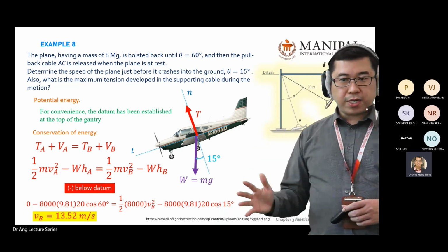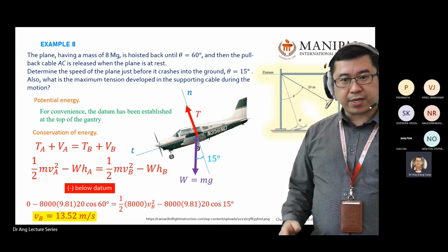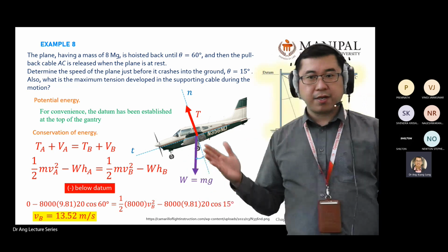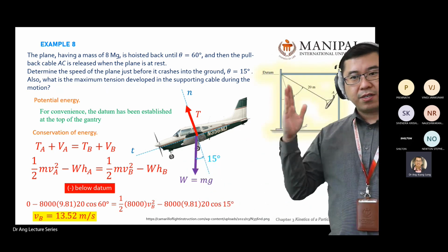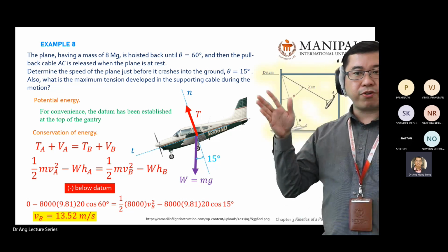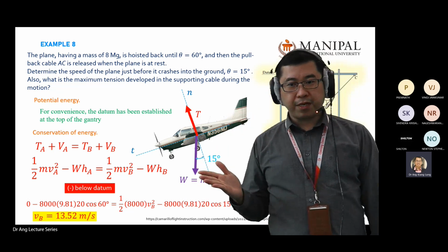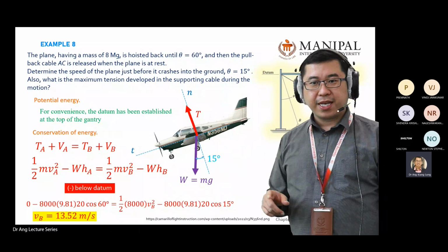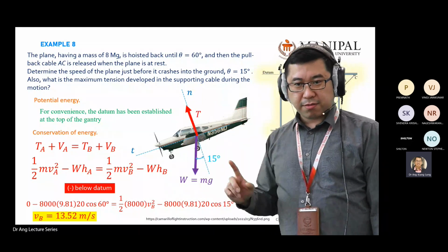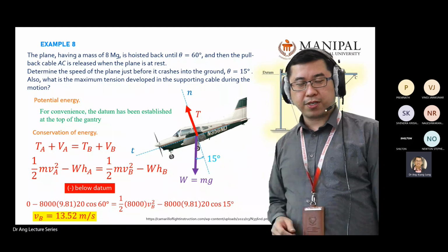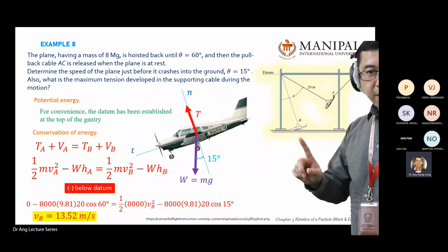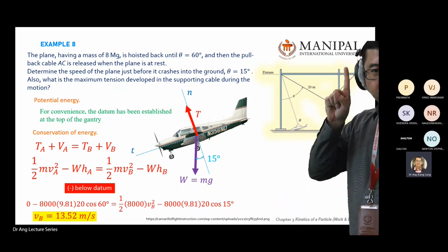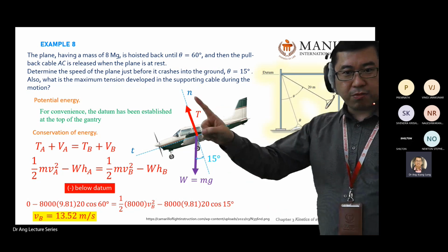Okay, so up to here, I hope every one of you understands what is happening. The numbers will change in the test and in the final exam, as long as you understand the standard procedure. First, read the question, convert the question into a free body diagram. Weight will be the normal thing that you will see in your free body diagram, and axes will help you to draw your forces. In this case, if you are aware, this one is moving in curvilinear motion, or circular motion, that's why you are seeing normal and tangent axes.